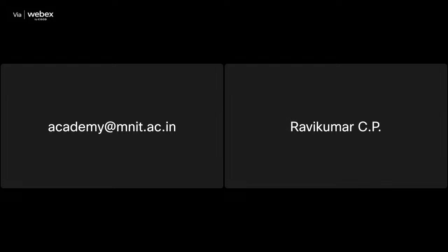The module called full subtractor takes three inputs, A in, B in, and borrow in, and its purpose is to compute A in minus B in minus borrow in, right? And it produces the difference output and the borrow output.